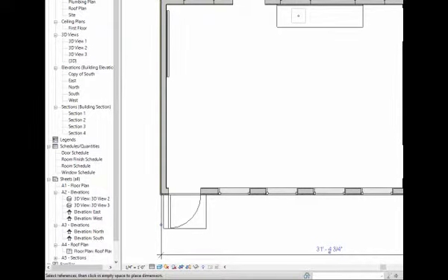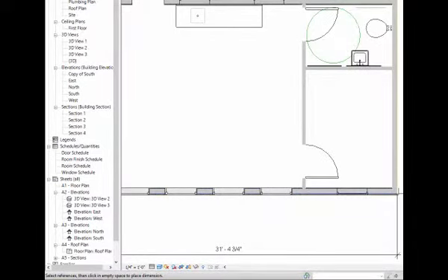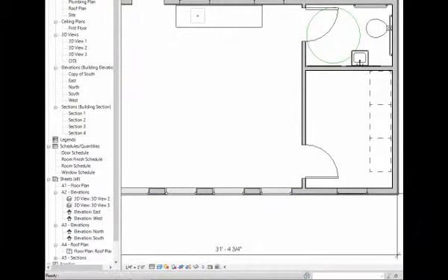As a good starting point, I want you to try this on your own models if you have them open. See if you can say faces of core. If I have faces of core, I don't even have to get in there very close. I can just click near the core and it'll hug up to it. It'll know what I'm trying to do. See if you can get a good overall dimension going in the other direction too. At the highest level, I'd love to know just how wide is the building? And the building's basically 31.5 by 17.5. That's the highest level information, and just even knowing that is going to be useful.